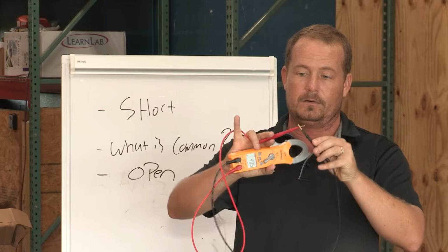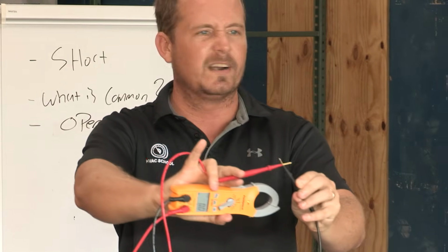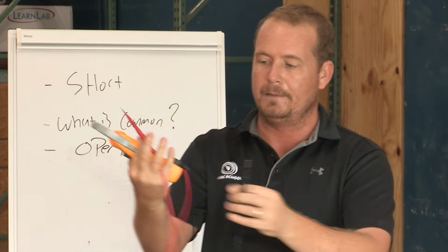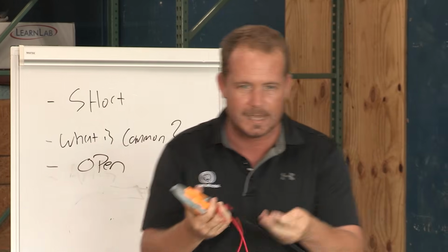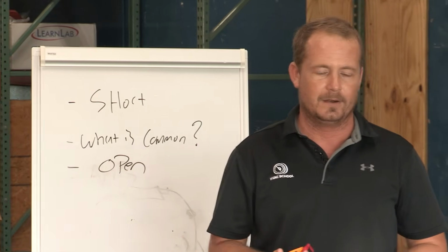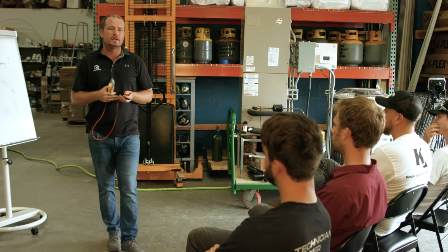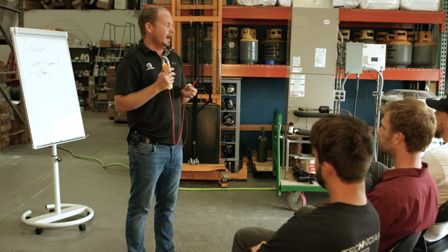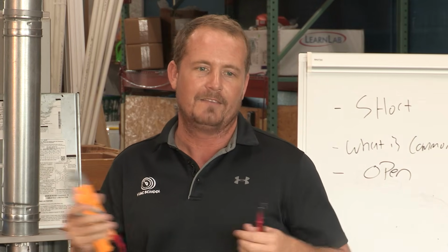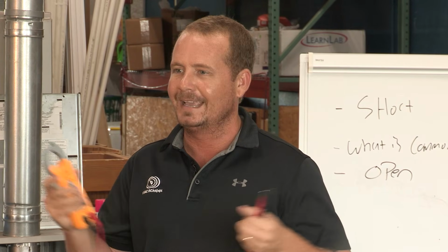If I put them together, what's my readout here? 0, very near 0, right? That means that my leads are intact. Because I wouldn't want to start trying to test and be like, I'm not getting anything. Also, be really careful with the term no. I'm getting no ohms, or I don't have any ohms, I'm not getting any.